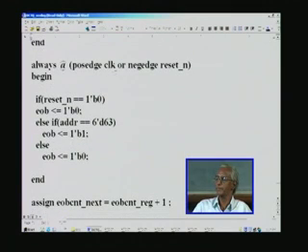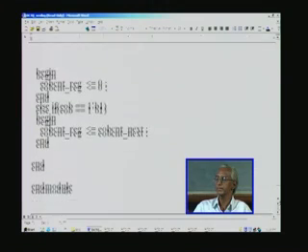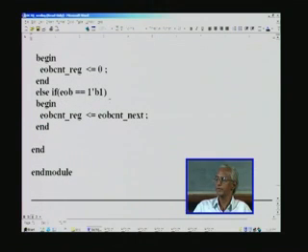So, in the next step what we do is we had used end of block. This is generated by just examining address equal to 63. This is the running address of the DCT coefficients, and 63 means it has just now processed all the 64 coefficients. So, we set it to 1, otherwise we set it to 0, and that is how we count this in the next using advanced increment for the end of block counter, which we process here, and whenever this end of block is 1, only then we increment the thing, that is how it is taken care. This completes the test module as well.